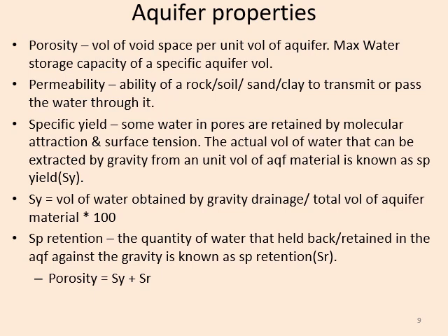Some of the properties are the same as what we have already studied or learned in soil mechanics. So first is porosity: the volume of void space per unit volume of aquifer. It is the maximum water storage capacity of a specific aquifer volume. Permeability: the ability of a rock, clay, soil, or sand to transmit or pass water through it.